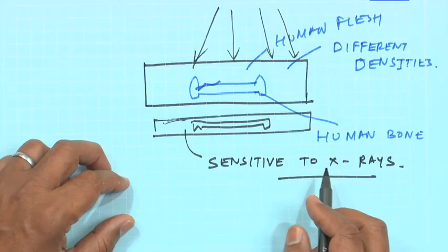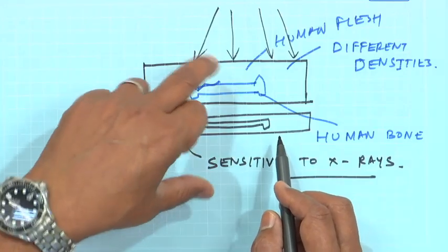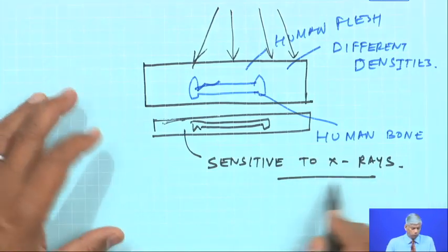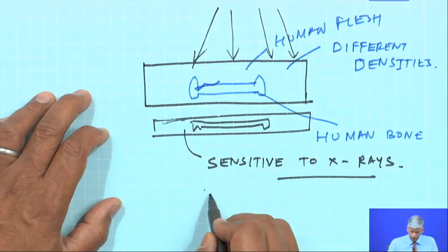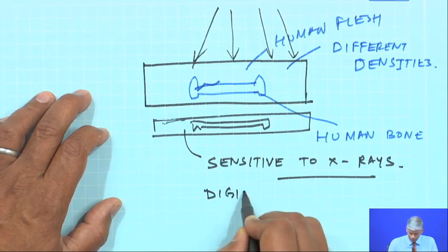So, because of the density difference, they can say there is some heavy metal, gold has a very high density compared to your normal clothes or whatever you have put in your suitcase. So, that is how this is used. A similar concept is used to find out whether there is a foreign element, whether there is a crack. So, this is what is used, and of course, nowadays this film is being replaced with digital images.